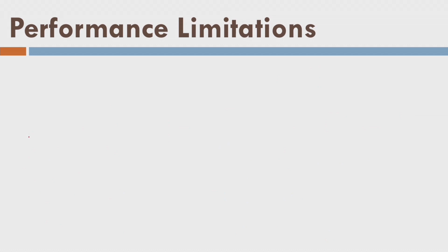So let us look into a simple numerical exercise here. Signal to noise ratio is 20 decibel. Baseline is equal to 2.5 meter. Lambda wavelength is equal to 5 centimeter or 6 gigahertz.